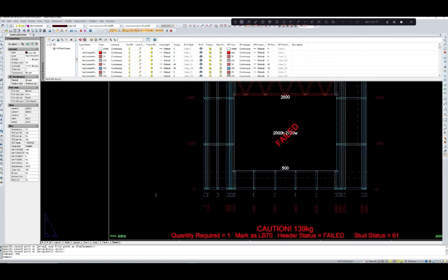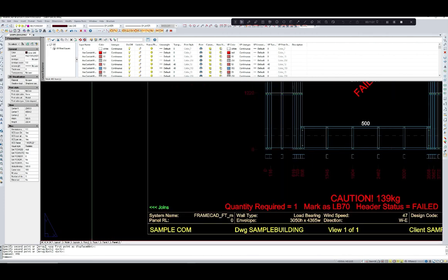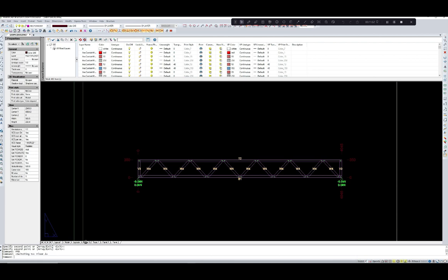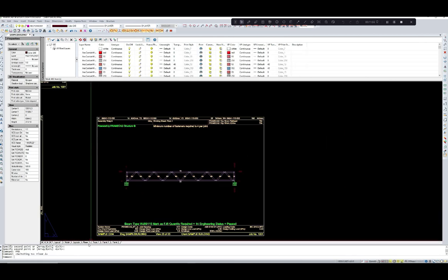So the next command after that is to export this file to CNC file for use in detailer file and providing the fitting file for the FrameCAD machine or any other machine which is compatible with FrameCAD. So for that, let us select the CNC file of the floor joist. Go to the layout panel for floor, then the command for that is CNC, enter. So you can see the CNC is now complete.